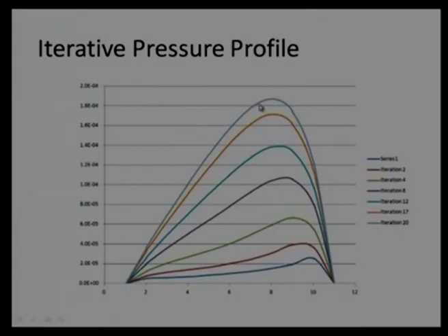That is clear, and when we use some additional technique like the over-relaxation technique, then there is a possibility of a sudden change in pressure variation. However, if you are not using any relaxation technique, then it will take slightly more convergence time, but there will be a definite profile and continuous improvement. Even if the improvement is slight, there will be continuous improvement.